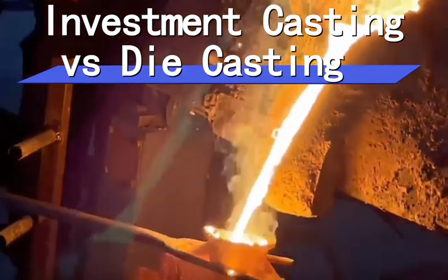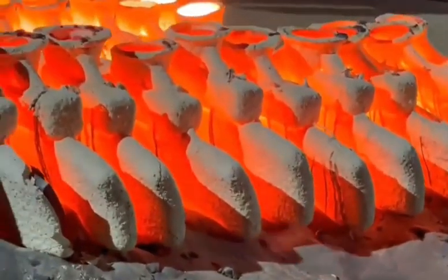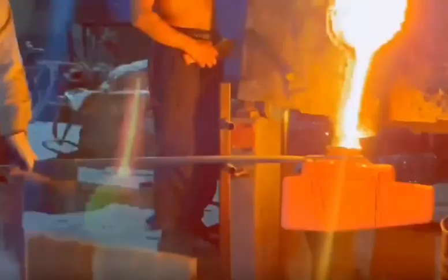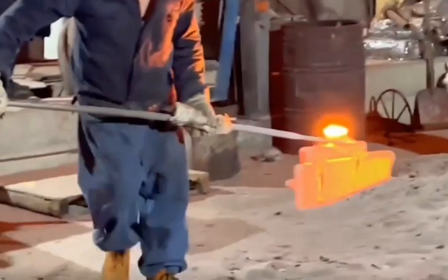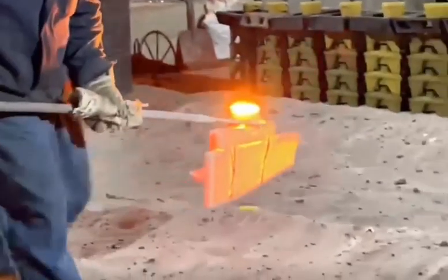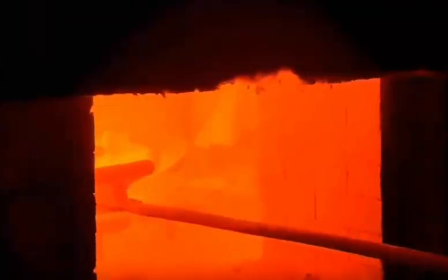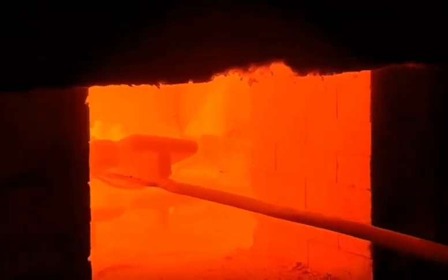Investment casting versus die casting. Investment casting allows for greater design flexibility, enabling the casting of complex shapes with precise dimensions, intricate geometries, and thin-walled parts. Although die casting can also achieve precise dimensional results, it cannot produce designs as complex as those achievable through investment casting.